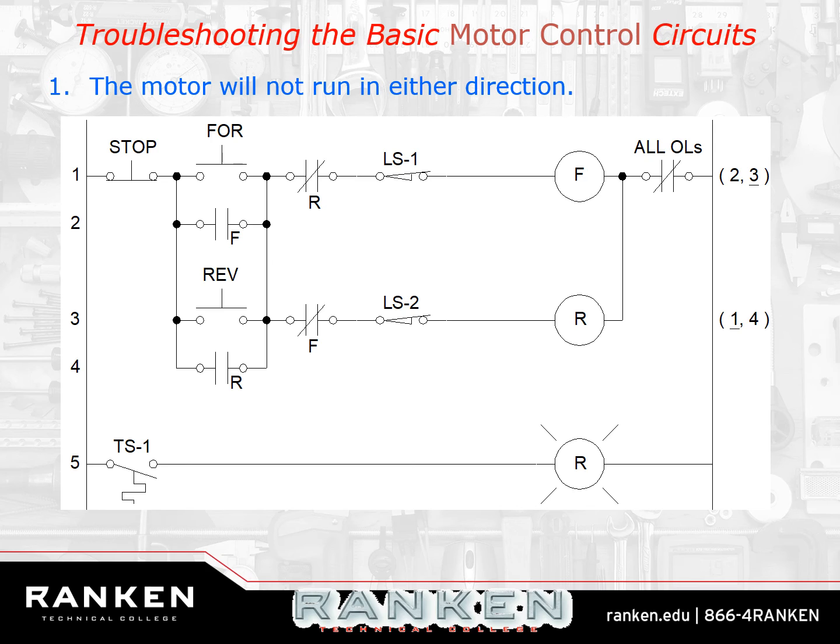Or I can go from here to here and see if I get source voltage. If the stop button is closed and the overload's closed, I should still have source voltage. Make sense? It's great, isn't it? It's a beautiful thing. Super neat.